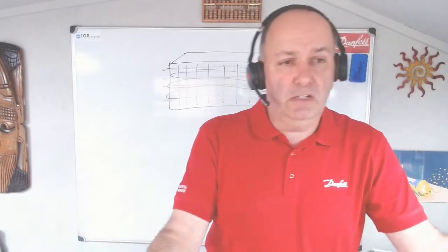Okay, a good question has come in from Abhijit. I hope that's near enough for close pronunciation. Can we generate auto alarm when heater fails? Yeah, I guess you could. I mean, every electrical heater pulls a certain amount of amps. You could monitor the amperage that's drawn from the feed that feeds those heaters from the defrost contactor with a CT device.